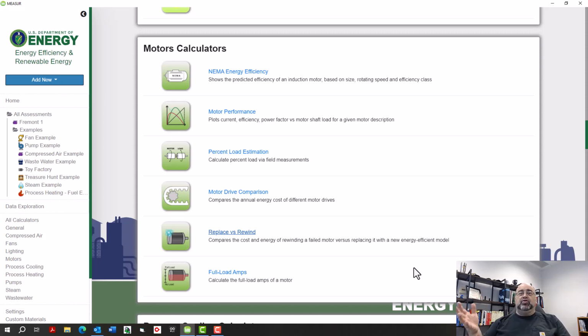And I'm going to show you how you can use this in order to make estimates of your load that are relatively accurate, look at your field efficiency, look at some of the things we talked about, like how do I get a quick measure? I only have a voltmeter and an ammeter. How can I go in and tell if I've made improvements? Well, if I know my power factor, which is usually on your motor control center, if you have relays, you can usually get that relatively easily. So you'll want to take a look at your power factor.